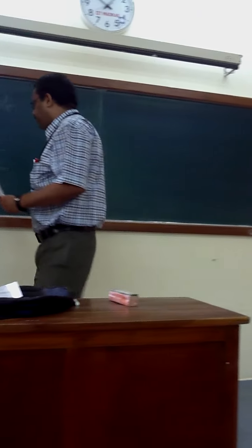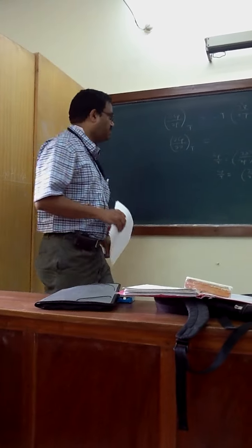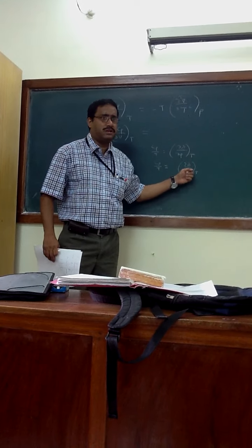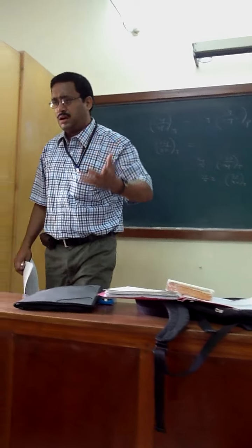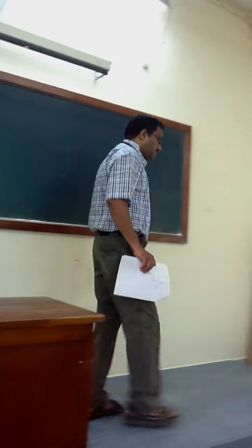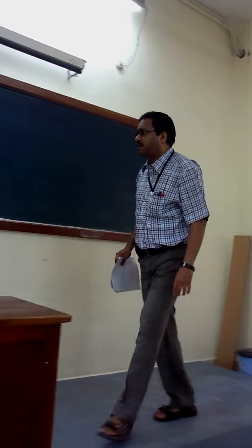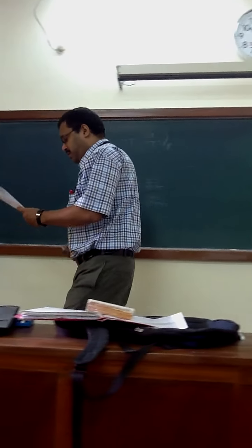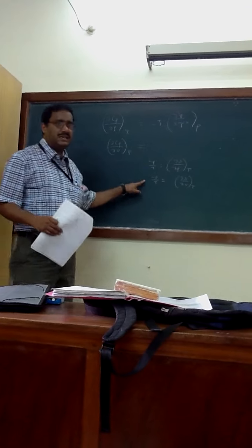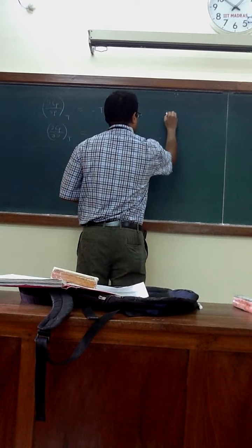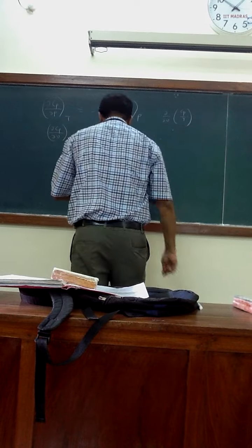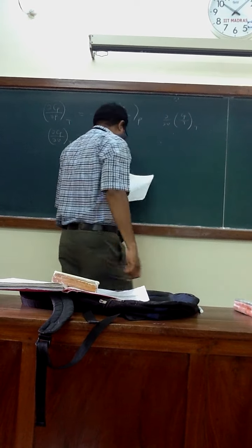And then how will you proceed? The advantage of this formula, and why I am taking it, is that these come in the Maxwell relationships, and this will directly give the property estimation. With that you can directly correlate your variation with the material properties. That's one of the major advantages. So what's the next step for dou Cp by dou V at constant T? First step is dou by dou V of Cp by T at constant T. What will you get?